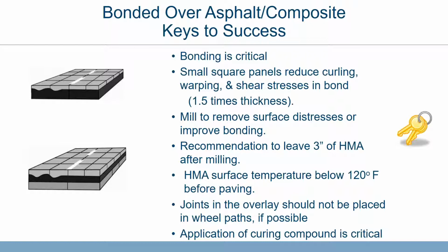We have a recommendation to leave 3 inches of asphalt after milling. I know that's another topic that's going to be discussed as we put the new version of the guide together. This was a conservative estimate that was made in part because some of the conditions that we see these pavements in, when we pave on them, we've got to oftentimes have a platform from which to work on with the construction operation. And we found that if we get into considerably thinner pavements than 3 inches, we sometimes, depending upon the base that they're sitting on, would run into problems with those construction activities or